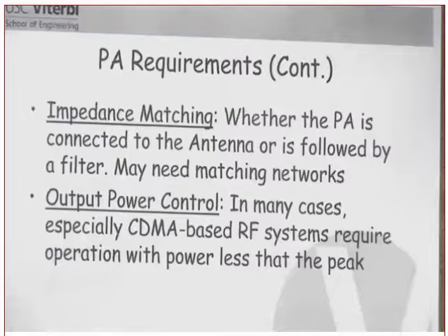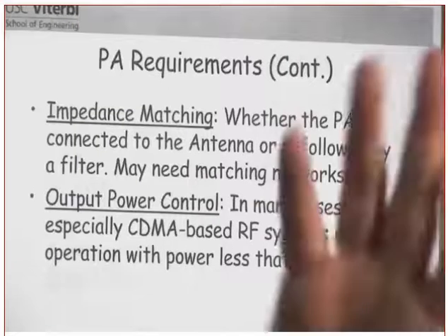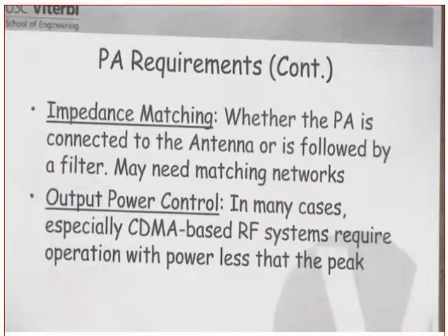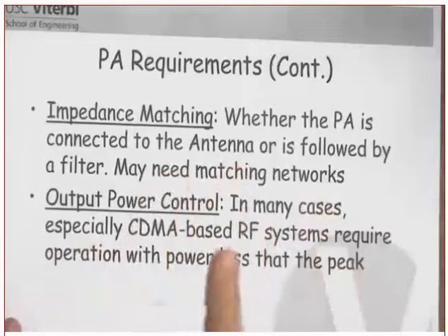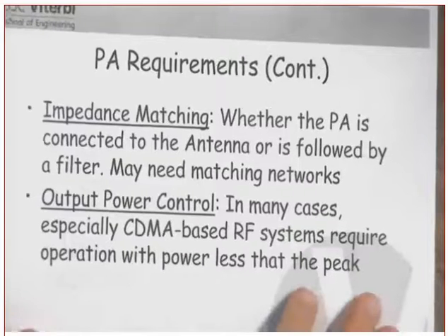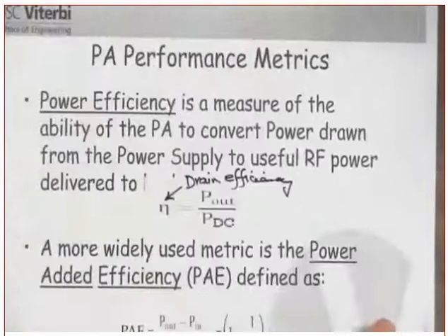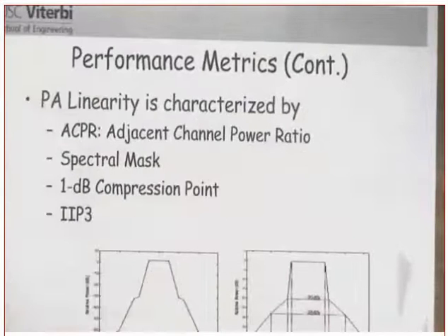So what this means is you apply a power control mechanism in which, if the mobile unit is far away from the base station, the base station will tell it to increase your power. If it is close enough, the base station tells the mobile unit, lower your power. Are you following me? I don't need that much power from you, you are close to me. Did you get my point or not? Such that the received power is almost the same, regardless of whether you are far or whether you are close, because the transmitter power will be different. Clear? Okay, good.